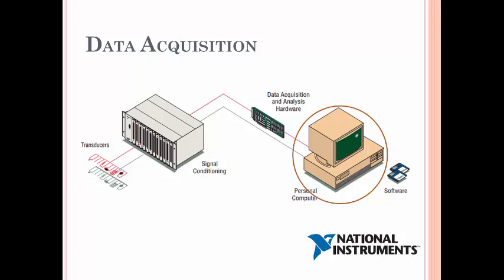Now, how does the personal computer play a role in data acquisition? It actually determines the speed at which the data is acquired, and recently the PCMCIA protocol has made it even more flexible and convenient to get data. The limiting factor in the personal computer is, however, the hard drive, because the disk access time and the hard drive fragmentation significantly reduce the maximum rate at which data can be acquired and streamed to the disk. The software and its requirements will be detailed later.